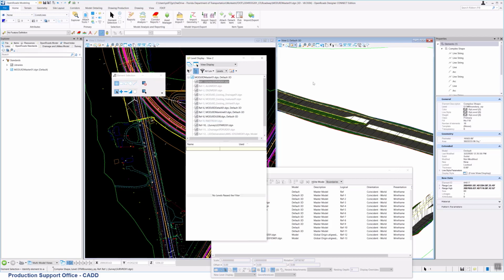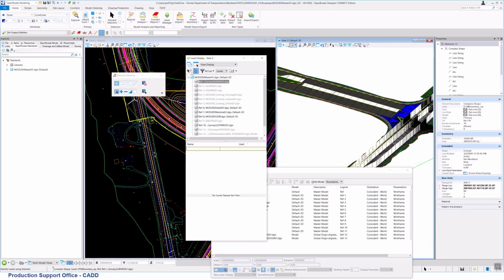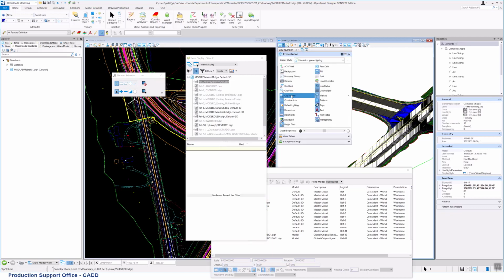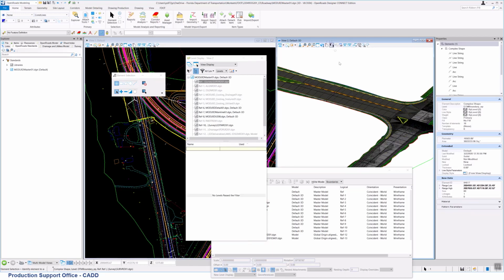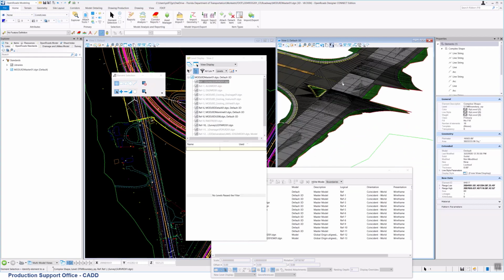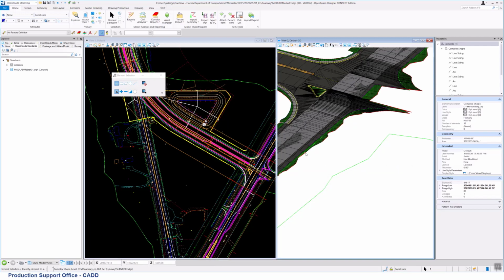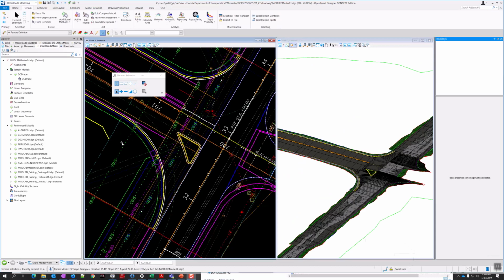Okay, since we're setting up for visualization and I have the level display on, I'm going to go ahead and turn off constructions because we don't want to see any of those extraneous lines. So we need to close out level display and reference display, and go over here to the terrain tab of the ribbon. We're going to go under additional methods, click the drop down there, and choose create clip terrain model.